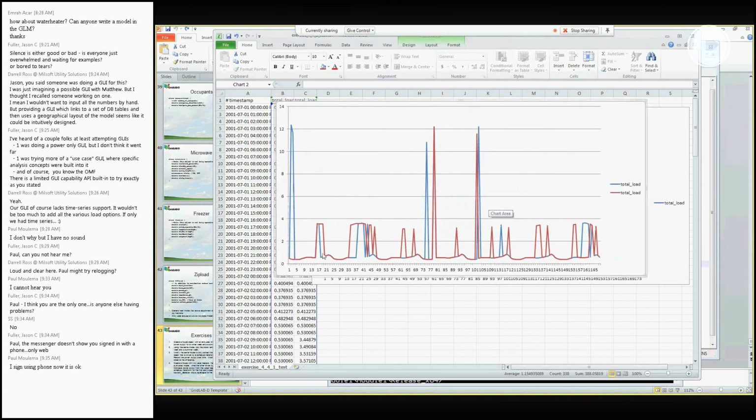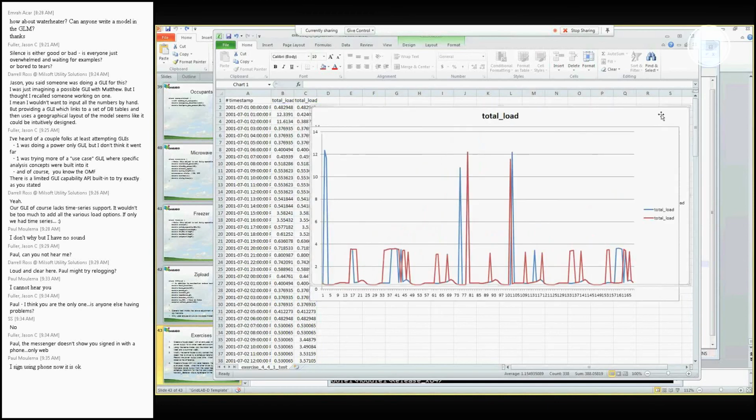So you can see here that by affecting the cooling set point, we actually affected the behavior of the way the system worked. Because this cooling system was set to be at a much cooler temperature, you can see that it's running more often. In fact, if we had measured the energy in the triplex meter, we would have seen that the measured energy over that 7-day period would be a lot greater in the second case, in the red case there, because you have a lower set point, so you're operating less efficiently.